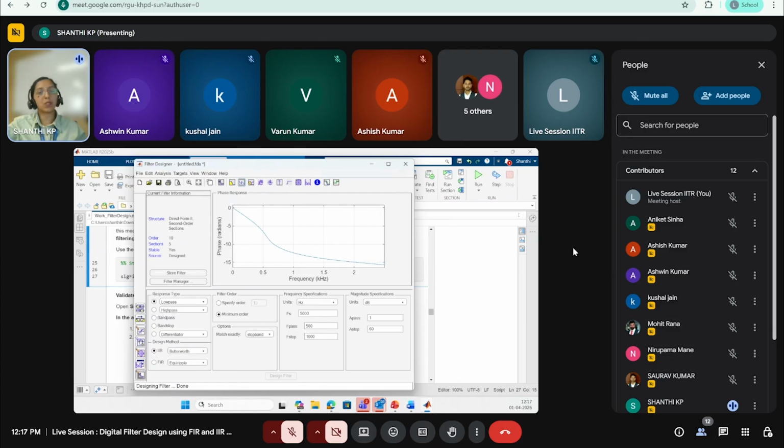And obviously the curve is not a straight line. It bends noticeably with a steeper change in the phase at lower frequencies and a more gradual change at the higher frequencies. So theoretically, we know that this curved phase characteristic is typical of an IIR Butterworth design, and is a visual indicator that the filter does not have a linear phase.